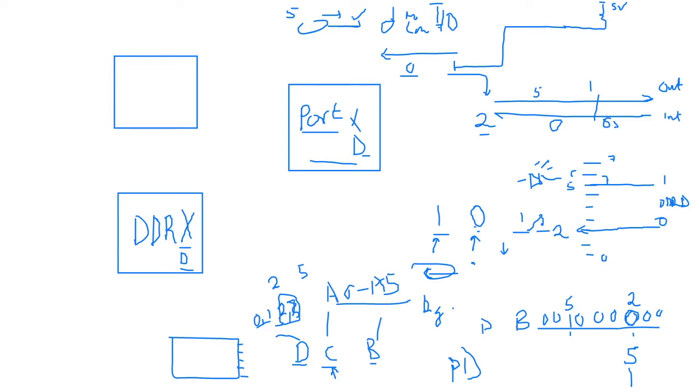Now, in order not to confuse ourselves, let me put 5 volts here so we don't confuse the pin. It doesn't hurt to set the LED pin off. So with the port, we are actually doing a digital write, but this digital write is combining both the pin mode and the digital write, because before in pin mode we could just do pin mode input pull up. So we are using a digital write to achieve a pin mode here, but at the same time we can do two things at once, which is the benefit of using ones and zeros. We get to combine stuff, right?